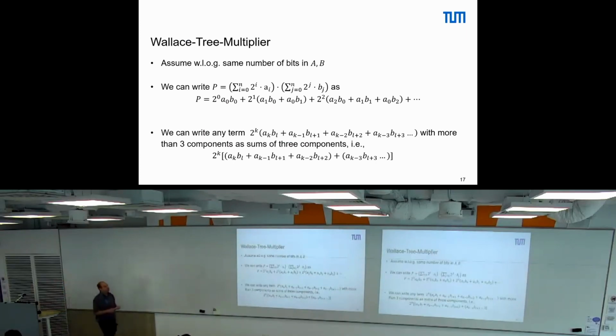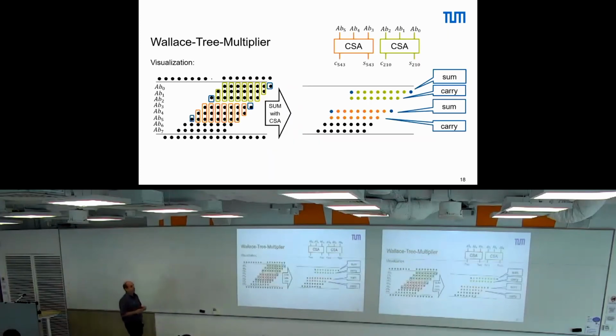but we can split our multiplication into other parts. Namely, we can always collect 3 or later 4 terms that correspond to the same power of 2, add them up, and compress them with our carry save adder. And then we can start to do this in parallel. So what we effectively have then is this Wallace tree construction, the Wallace tree multiplier, which I said the day before yesterday that I would explain with the multipliers. So we first want to do this with carry save adders.